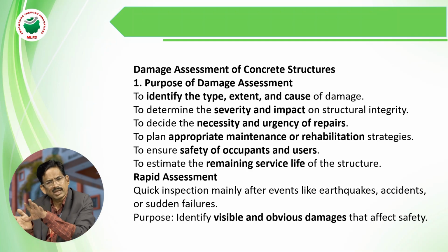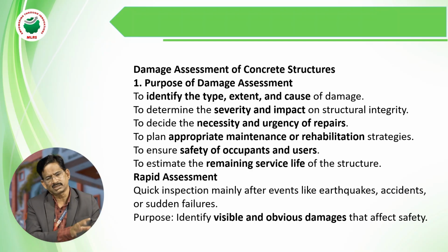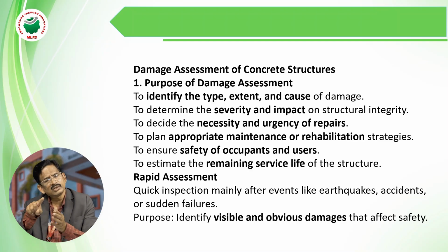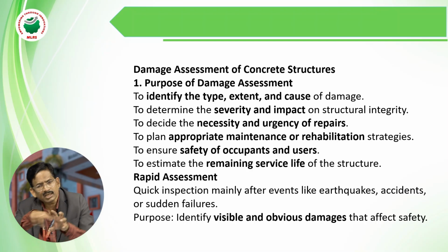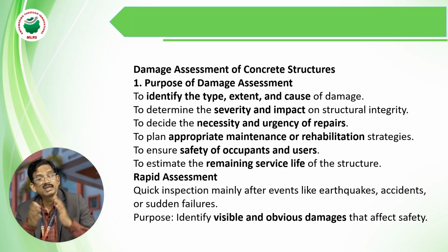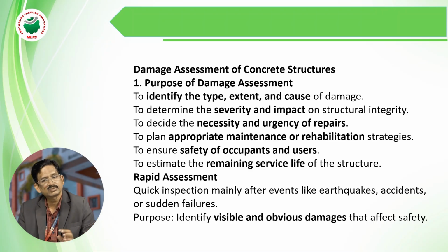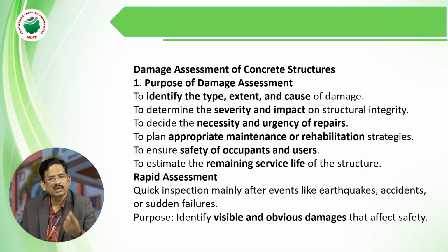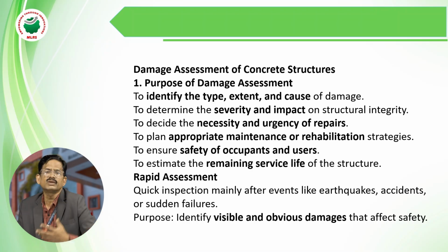So that's why we have to see all the possible things. You can check against the torsional moment also, just like a twisting moment. Against the torsional moment also, we have to test whether the building is safe or not. That's why in the design of RCC structures, we have to decide short-term deflections, long-term deflections, torsion, shear, bond, everything.